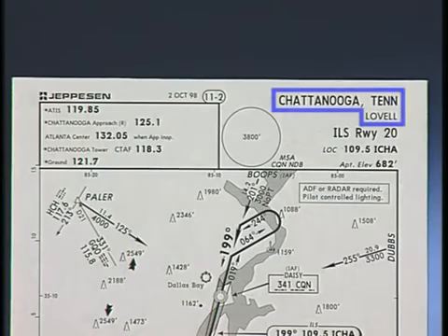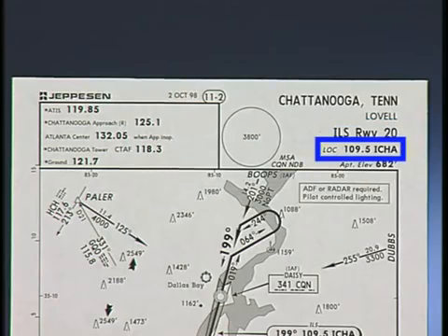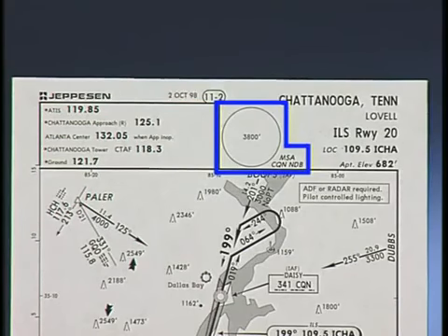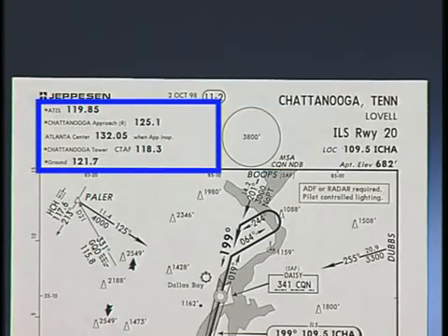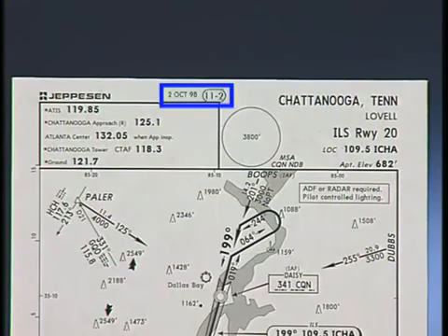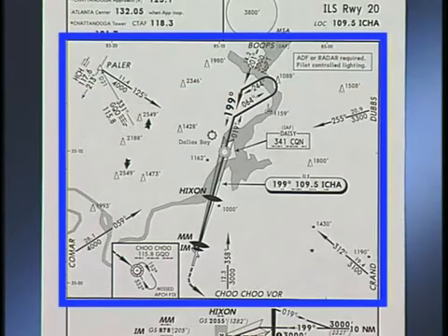The heading section identifies the city, state, and airport name, the instrument approach procedure, the primary approach facility, airport elevation, the minimum safe altitude information, or MSA, and communications frequencies in the order of use for arrival. The chart date, index number, and effective date, if appropriate, appear in the same location as on the briefing strip charts. The plan view portrays the overhead view of the approach.